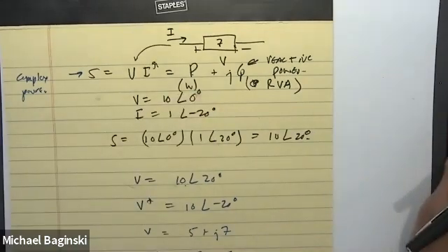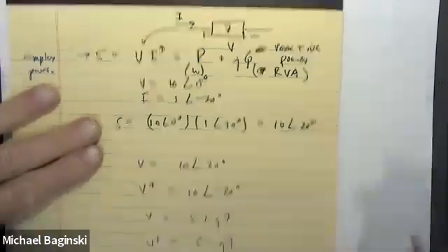Now, it will be clear to you in a second, and you're not being tested on this, but I want to make sure you understand that Q is a reactive power. It is never dissipated. Do y'all remember me talking about capacitors and inductors creating reactive power, or a power that is not dissipated? Any energy or power associated with a reactive component, a capacitor or an inductor, is brought back into the system. It's never dissipated. Follow me on that, class? Resistors dissipate power. They turn it into heat mainly. Now, capacitors and inductors don't. So that's reactive power in a nutshell.